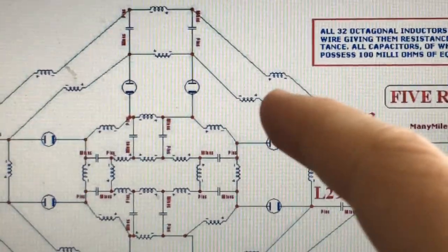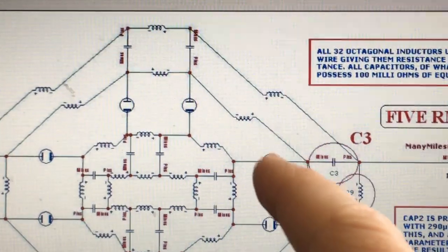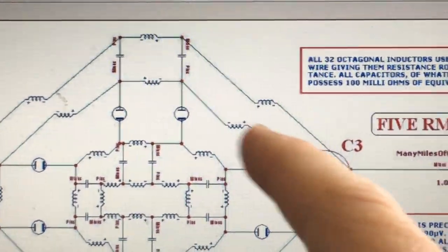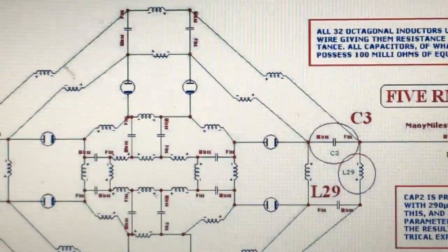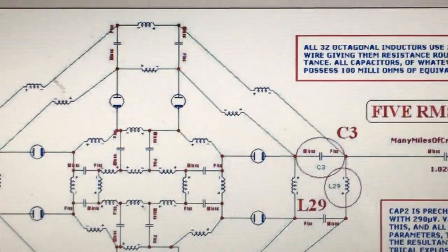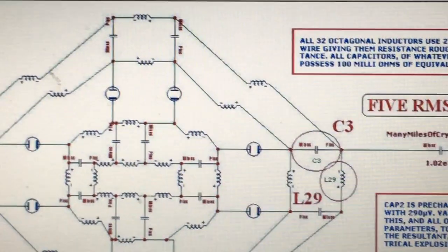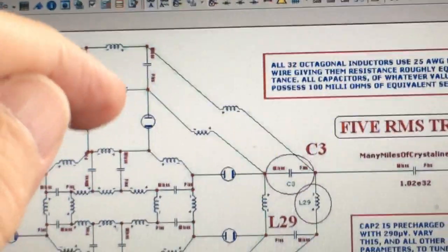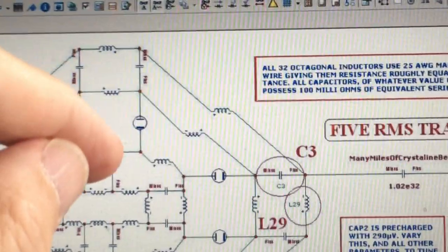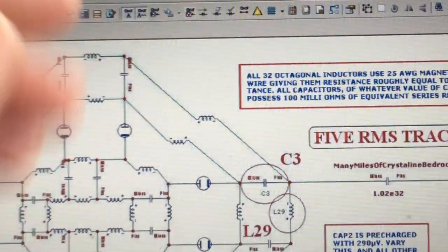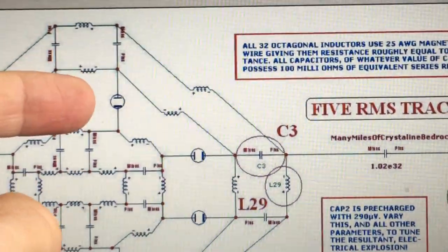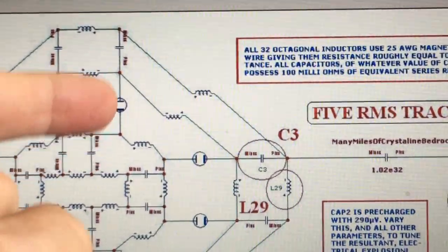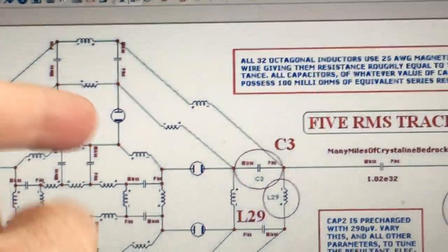Now, when we come to the middle zone, again, it's about the same, because a spark gap is kind of like a capacitor part of the time, and the other part of the time it's a capacitor whose dielectric has broken down, and you get arcing through pinholes, leakages, through the dielectric barrier that's in the capacitor, which represents the arcing across the two electrodes of a spark gap.